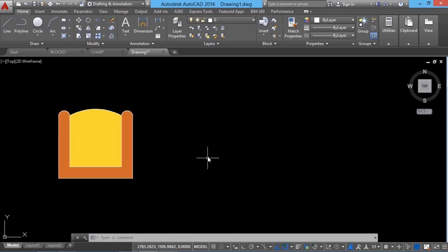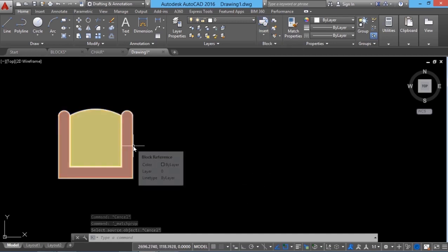You might sometimes think that the definition of this particular reference is that external drawing. In that case, any changes performed in that external drawing should get reflected here, but that will not happen. So the actual definition of this reference is created right in this drawing. Let's check that out. I'll click on insert command and you can see that the definition is created here, and the software establishes a link between that definition and this reference.